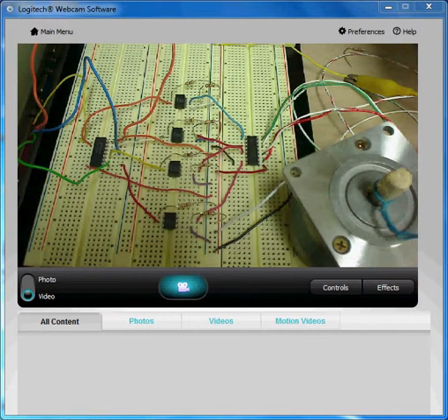It has 6 wires. When you measure the resistance, you can identify that the black one and the white one should connect with the power supply. The green one and the green-white one are a pair of coil. The red one and the red-white one are another pair of coil. For the connection of these coils and the according sequence, you have multiple choices.